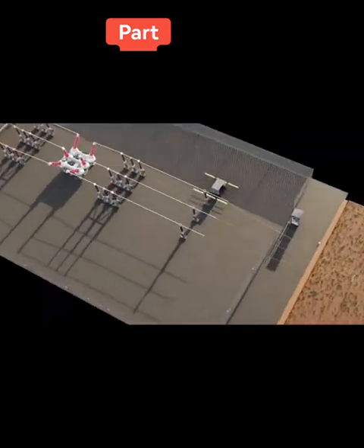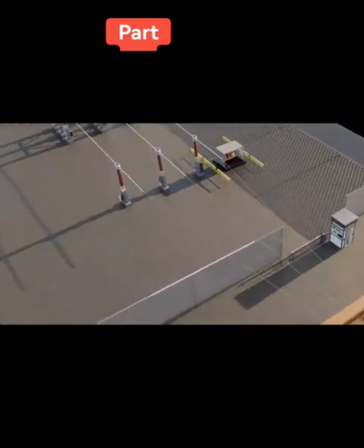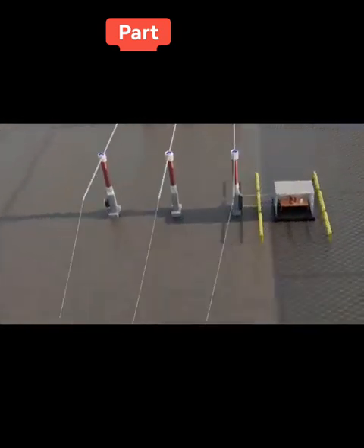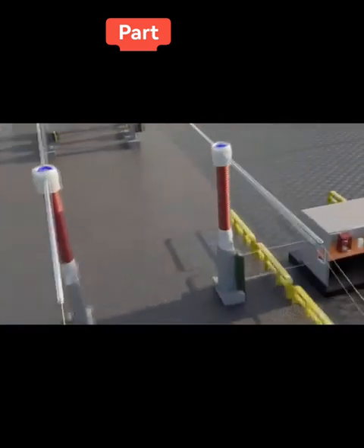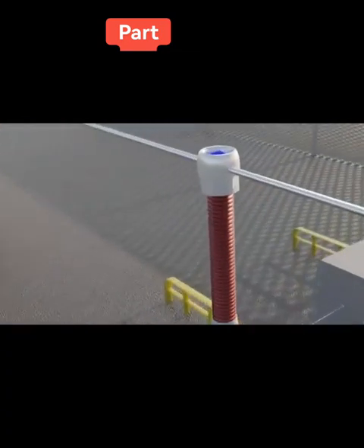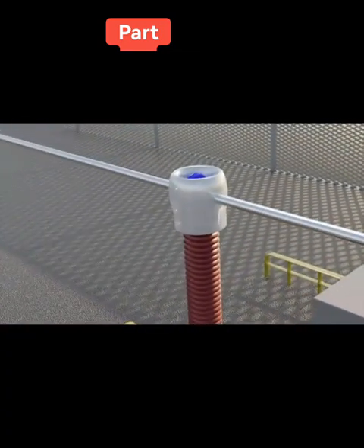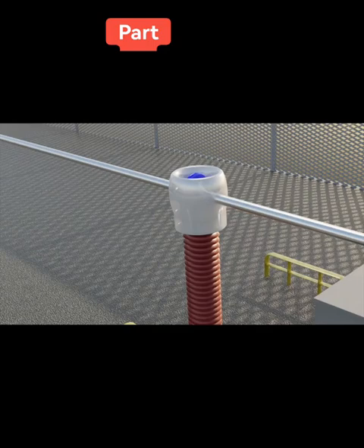But they are not the critical part of a protection system that we're going to talk about today, so we're not going to be discussing them. We're going to be talking about the current transformer, also known as your CT. We know that your CT has the ability to step down your current to a very measurable, appropriate lower value. This is absolutely necessary because the fault current is way too high to be measured directly.